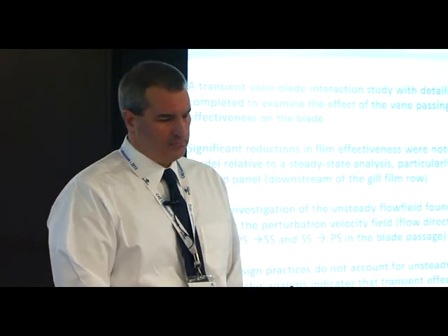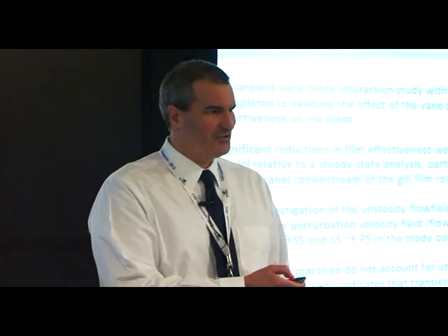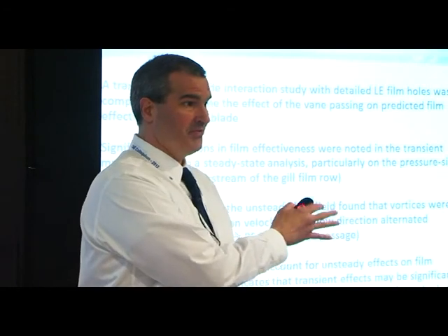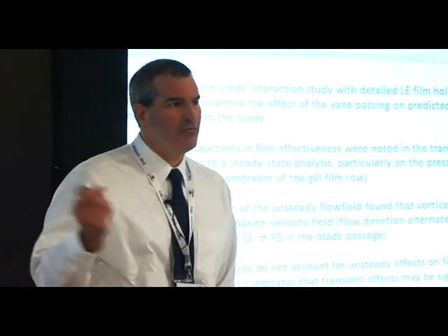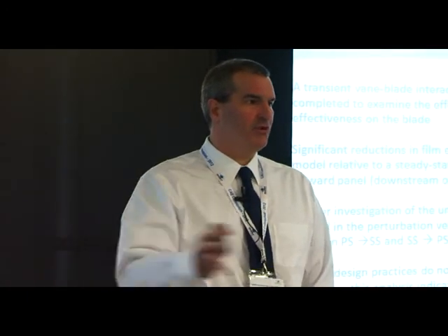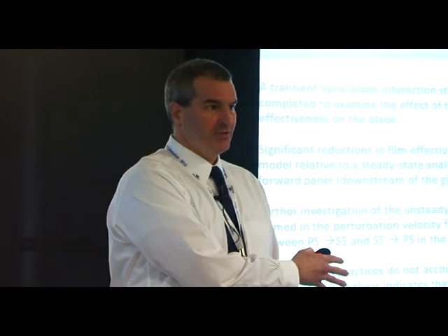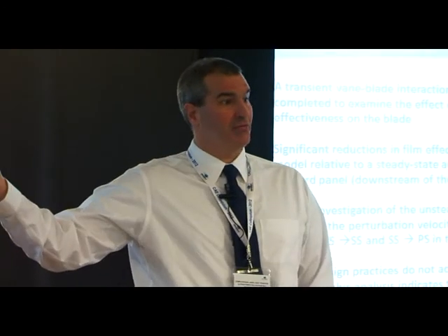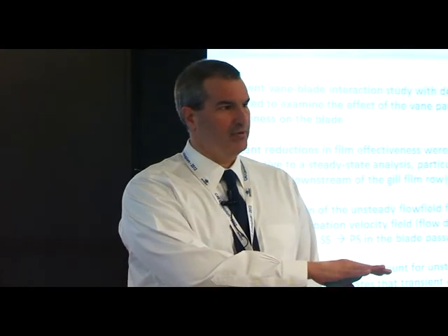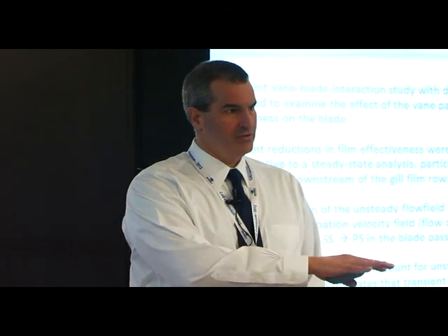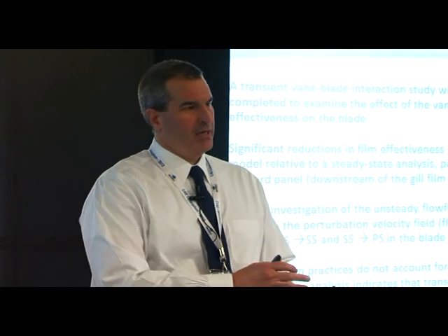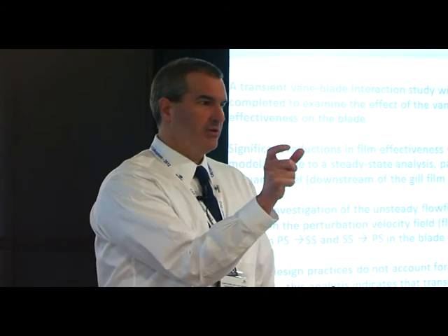There's a lot of answers to that question. There were three questions there. First, is it first order in time? We were just looking at trends. We had no idea what we were going to find when we started out in this case. So before we do the really complex calculations with the higher order methods, we thought, let's just see what we get with first order. And then the pseudo time stepping is only for steady state time integration. That's one of the methods you can use in CFX to get to a steady state solution. And we were really looking at modeling a steady state operation of that 3 millisecond window.